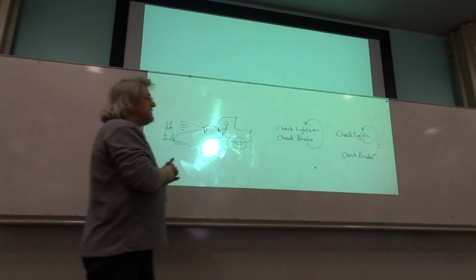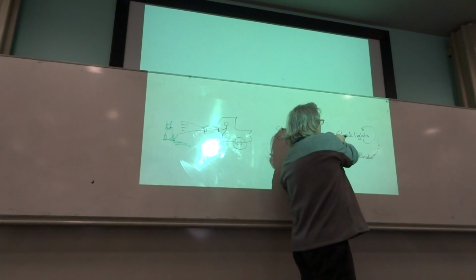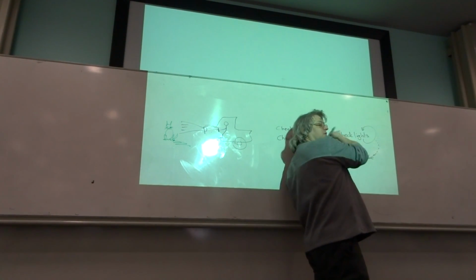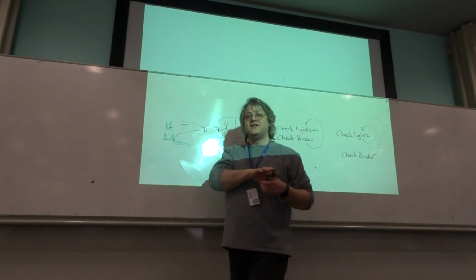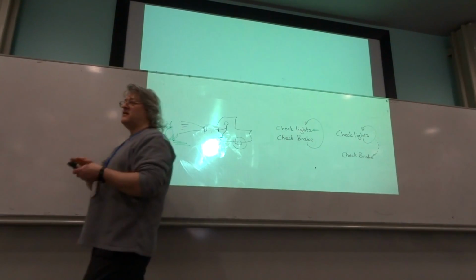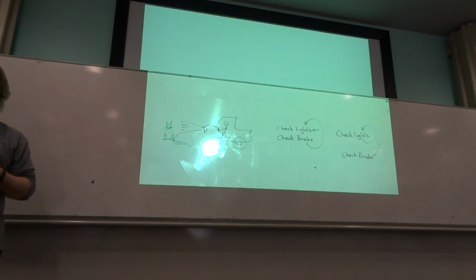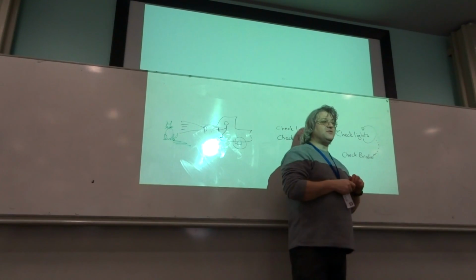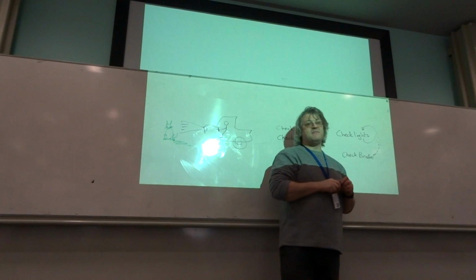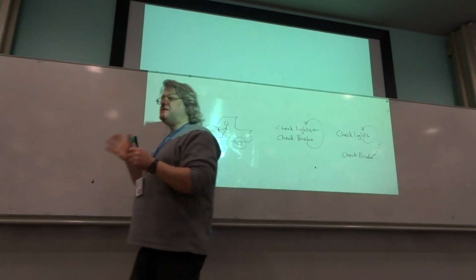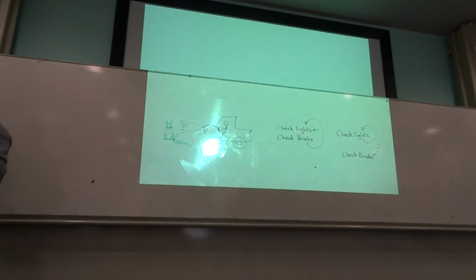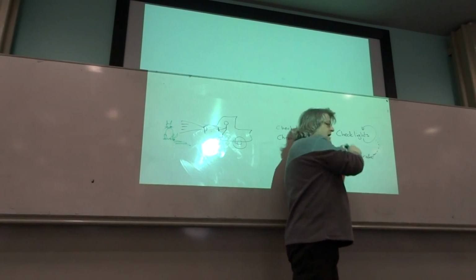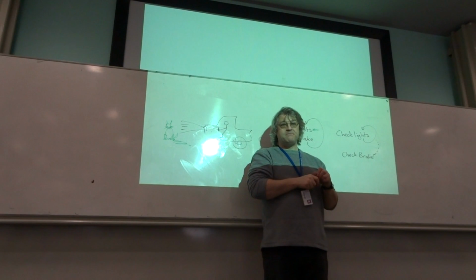So the concept of an interrupt is, under hardware control, you're able to stop the flow of the program, to suspend it, and to effectively start a new program in order to deal with the source of the interrupt. The 8051 and any kind of microprocessor that has an interrupt capability, it's basically implemented within hardware. Okay.